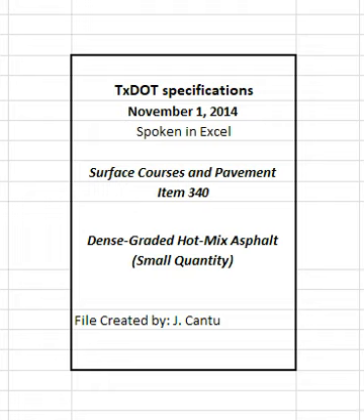2.8 Substitute binders. Unless otherwise shown on the plans, the contractor may use a substitute PG binder listed in Table 5 instead of the PG binder originally specified, if the substitute PG binder and mixture made with the substitute PG binder meet the following.